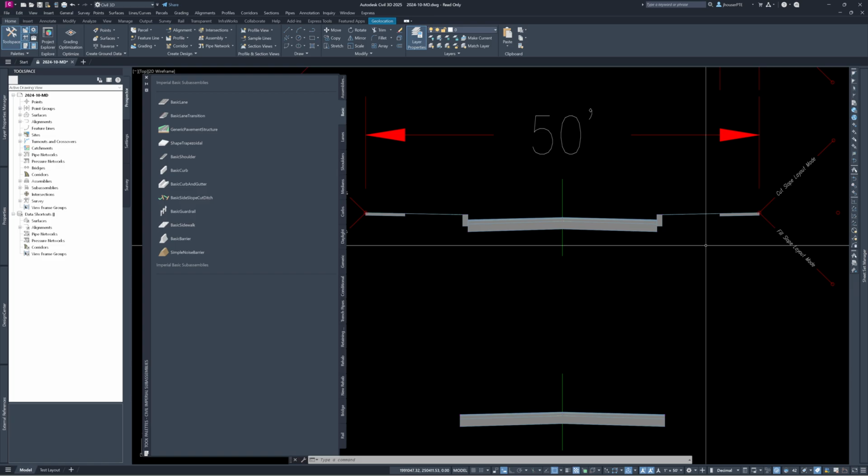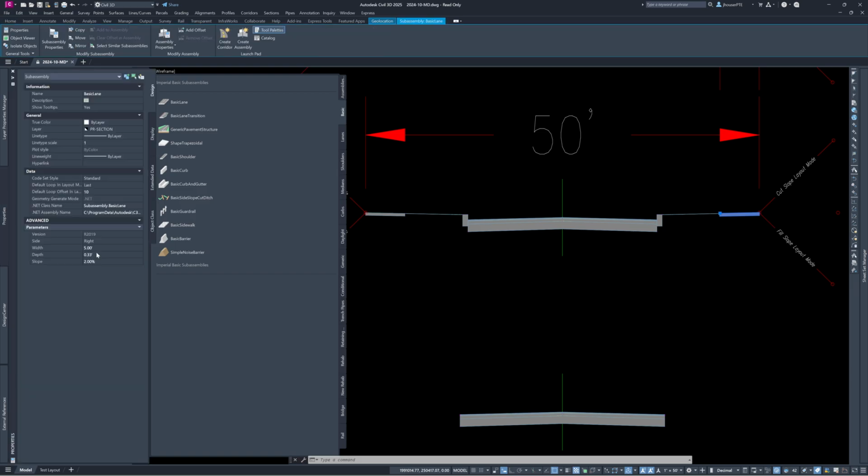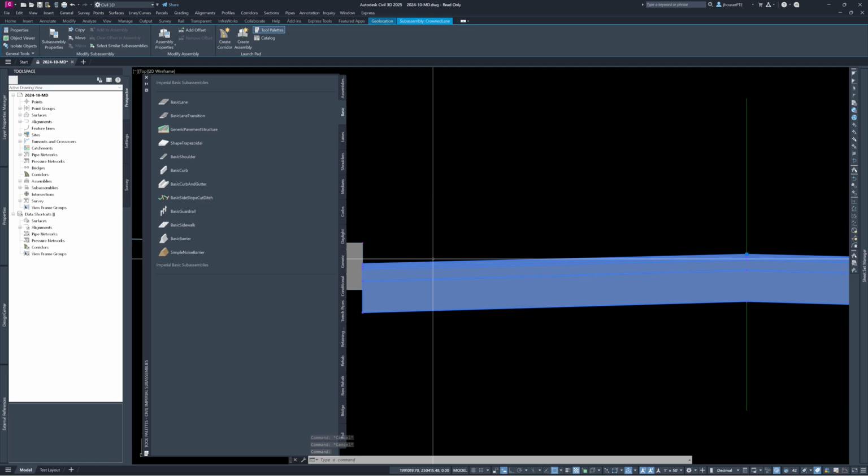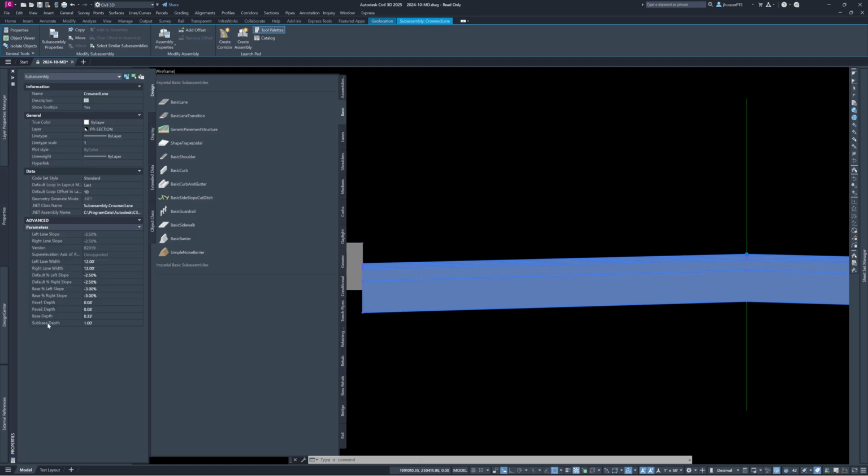Now, this one used a basic lane component, so that would have a slope of 2% with a depth of 4 inches and a 5 foot width. So there is a difference. This part here, you can see that there's extra lines in here just signifying the different parts of the actual stone, wearing course, base course, all that stuff is in there. On the properties, it has more settings. You could actually go through and change all those depths. This is our typical. It's easy to go to.